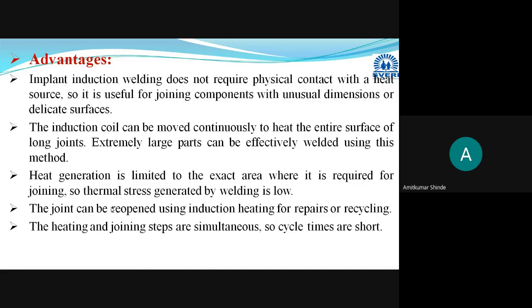Hence, the thermal stresses after welding are very low in high frequency induction welding, as you can control the heating area.